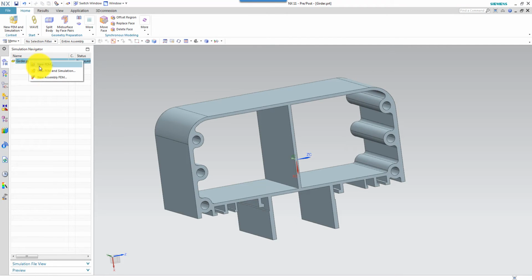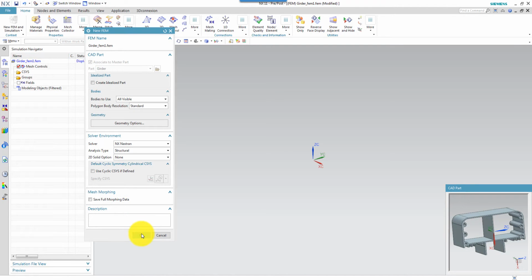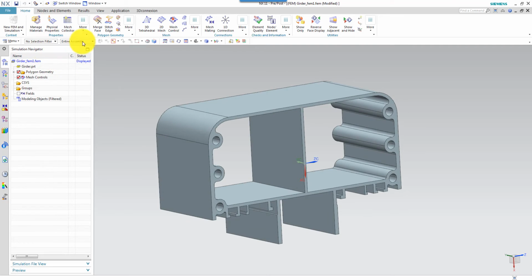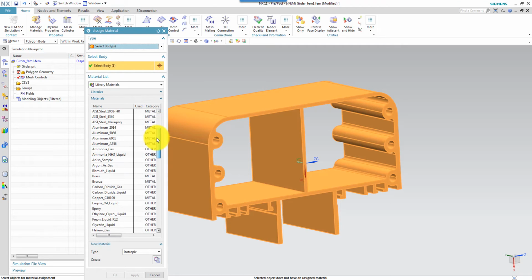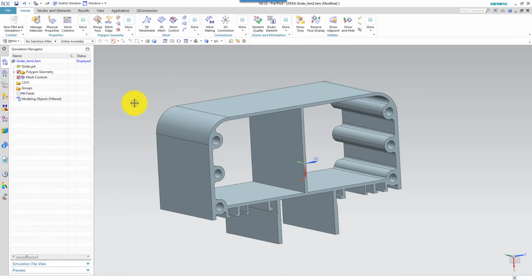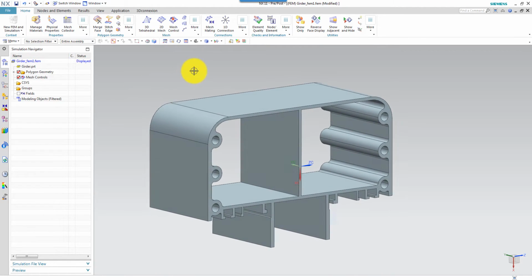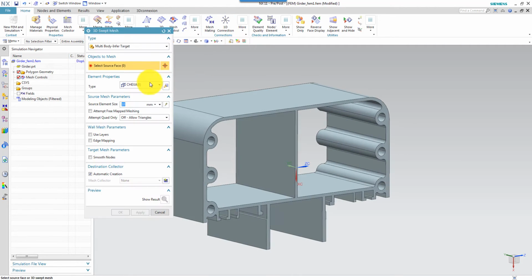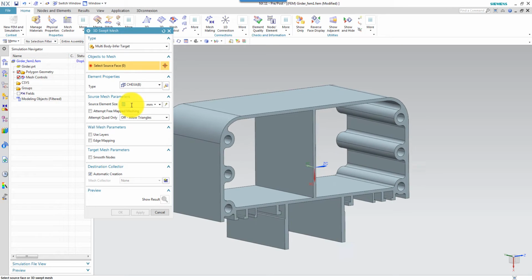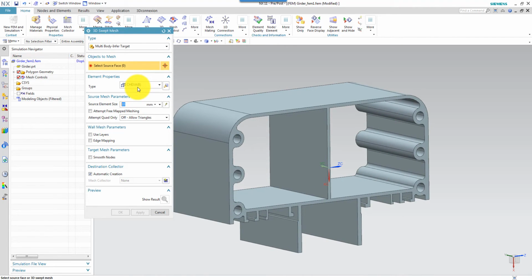I want to create a new FEM, accept the default name, the same options, and there we are. Again, apply the material, assign material, and this one is made of aluminum, so let's choose A356. So, okay. I don't want to use a free mesh on this one because it's an extruded part, and then I can always use a 3D swept mesh. I can use the same element size, 10 millimeters, and to make the simulation fast I just used CHEXA 8 elements. Should have used 10, I guess, but...